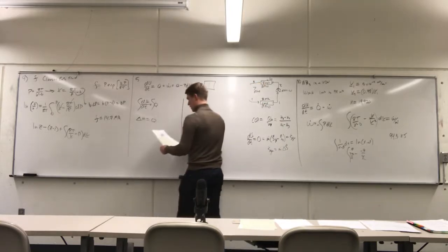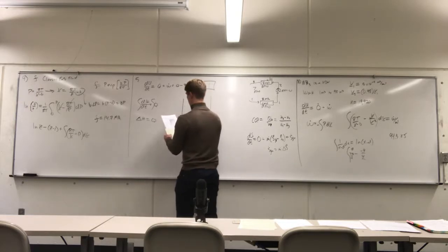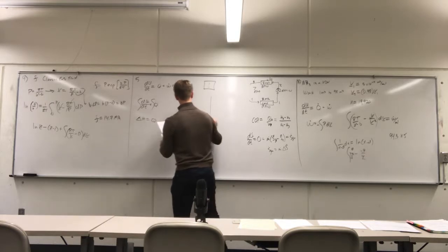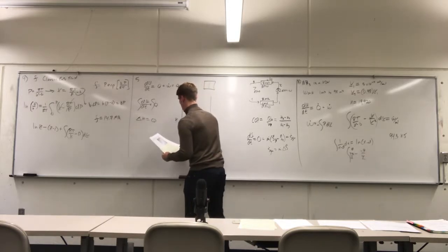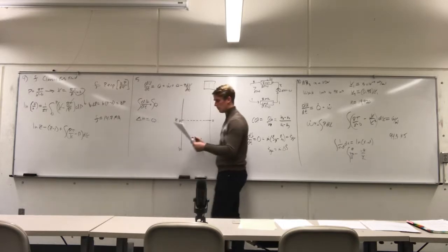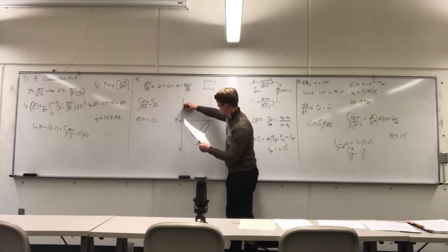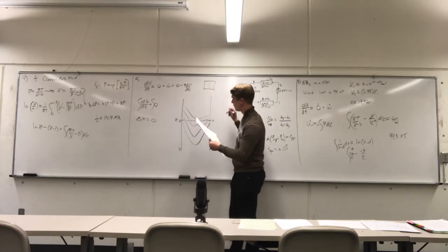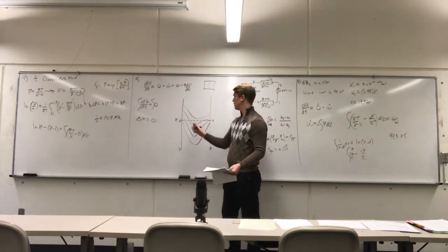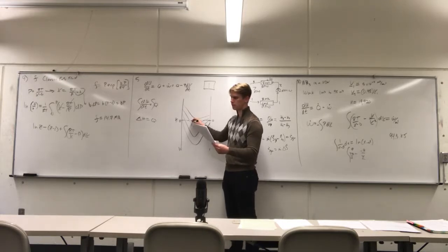So if we look at the table or the chart, this is the enthalpy. So this is 100%. Let's see, this is a weight percentage of. So this is water, and this is 100% acid. The reference condition is 0, and then we have a series of lines that kind of look like this. So if we did this adiabatically, we would mix to a point right here, which is about 40% acid, which is what the problem is saying.